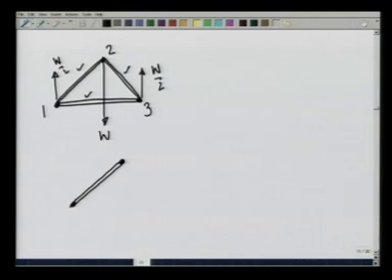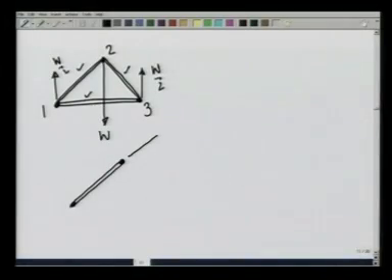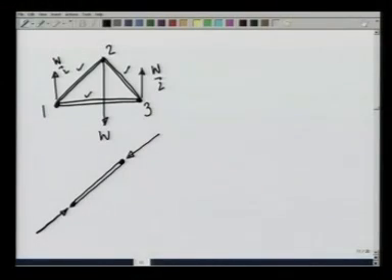And remember what I said in the beginning of the lecture, that if a body is in equilibrium under two forces, those forces are collinear. So, in this case there will be a force on this acting this way and a force acting on it this way at these 2 points. This is the only way these two forces can act, otherwise the body will not be in equilibrium.